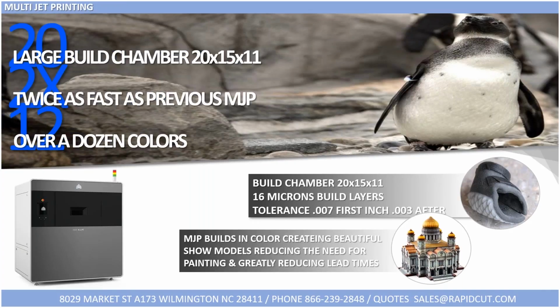Next up on our list of categories here is the multi-jet printing process. And what's exciting about multi-jet printing is that it allows us to not only use multiple materials, as you can see here in the little boot, it can also do multicolors, if you look at the example of the architectural model there. The chamber size is 20 by 15 by 11, typically twice as fast as conventional multi-jet, polyjet platforms, and over 12 dozen colors to mix and match to create a variety of different tones.